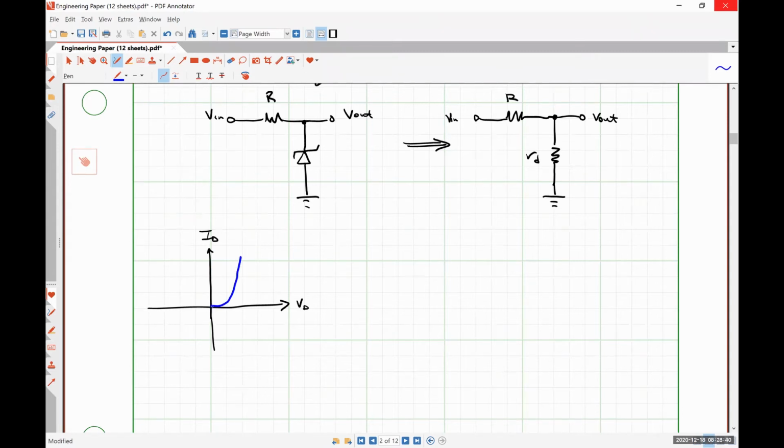But in the reverse bias region, once we hit that breakdown voltage, we effectively start passing any amount of current that we need. So when current flows through, it's pinned at the, or when it's sufficiently reverse bias, effectively the voltage is pinned at one specific voltage or very close to it. So there is technically a slope to that nearly vertical line, but it changes with current only very, very slightly.